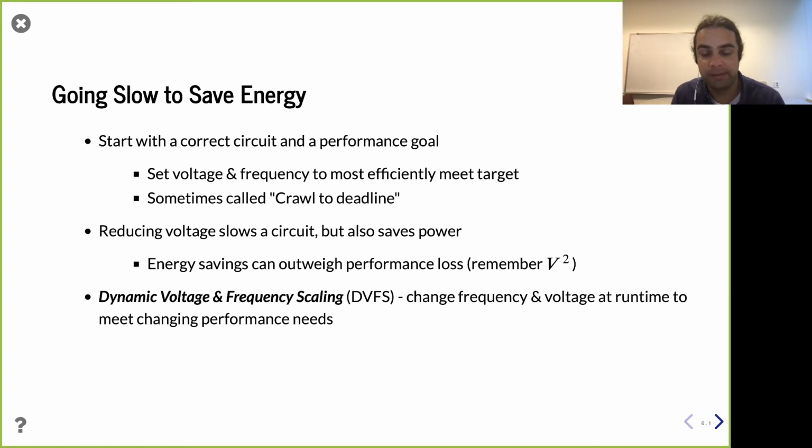There are people who design this in the physical design team. They're going to figure out, for this chip, we characterized that for every one of these frequencies we want to run at, what voltage meets timing. And they're going to know those voltages, so that when you change the frequency, you also change the voltage. Sometimes they pre-characterize the chips. Some very advanced chips actually have what's called a canary circuit, a circuit that is representative of the rest of the chip, and they can see if that thing is or is not making timing, and they can change the voltage on the canary circuit to then see how to change the rest of the chip. However they do it, the result is that if you want to increase frequency and go faster, it's going to cost you more juice, so you have to turn the voltage up. If you need to go slower, at lower frequency, you can turn down the voltage.